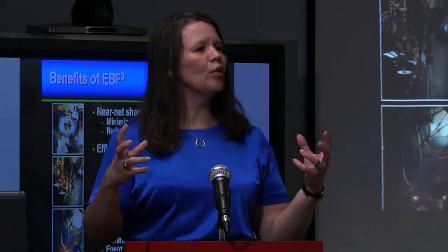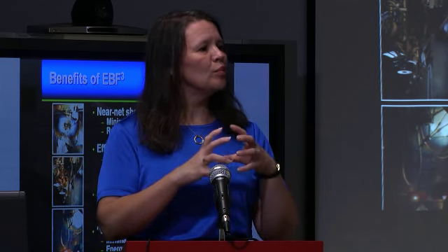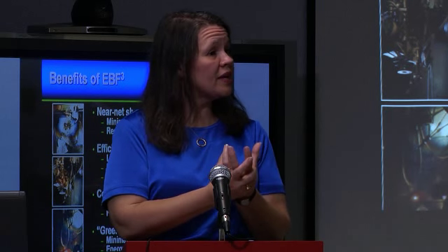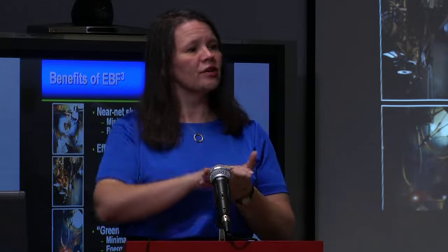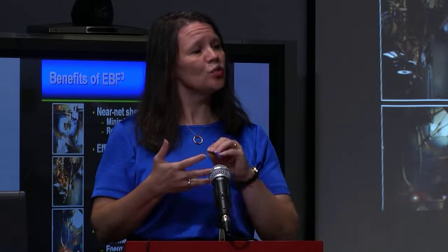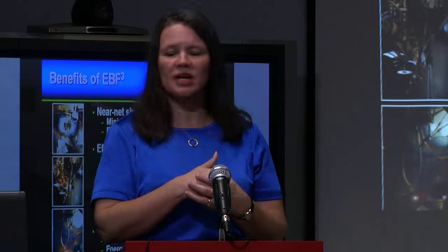The reason that we want to do this for aerospace parts is you can build a part, instead of building a lot of little parts and having to assemble it, you can build it all in a single piece just by building up the layers and designing it. It allows us to go more efficient on some of our designs. We can reduce the weight of structures by being more intelligent in the way we design the structures.